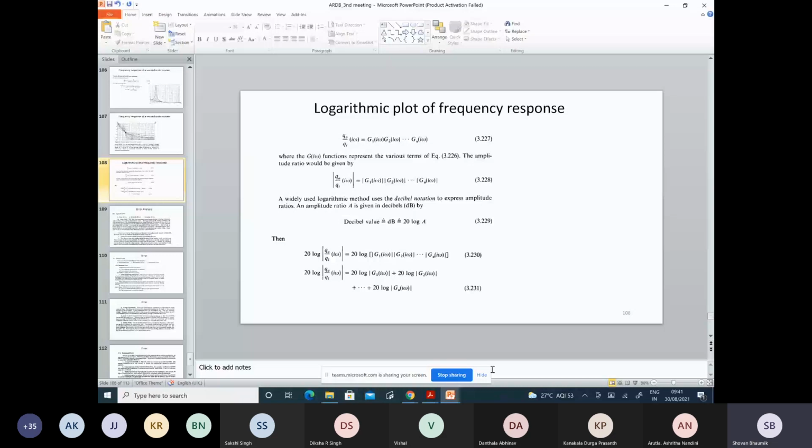So you take this for a series of input frequencies and you plot it on semi-log graph paper. Then for the different input frequencies, you have to observe the phase. How can you observe the phase? You make a Lissajous figure, which you might have read at some point. You superimpose input and output. There is an option in the oscilloscope, a knob or switch, which basically says make a Lissajous figure.